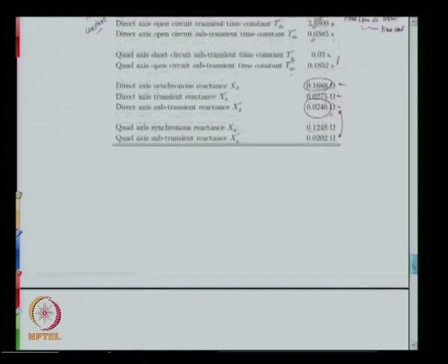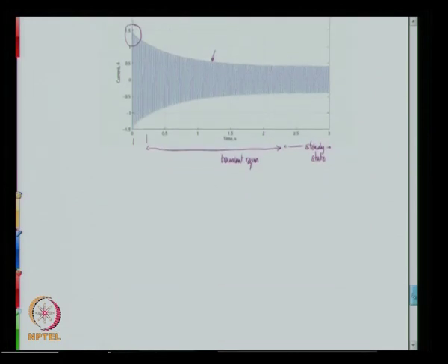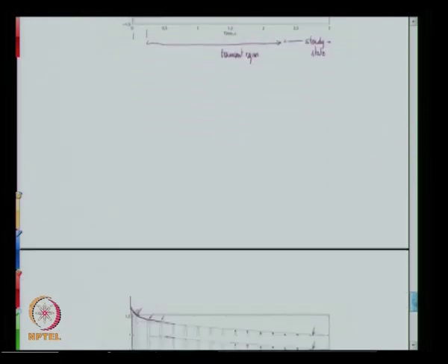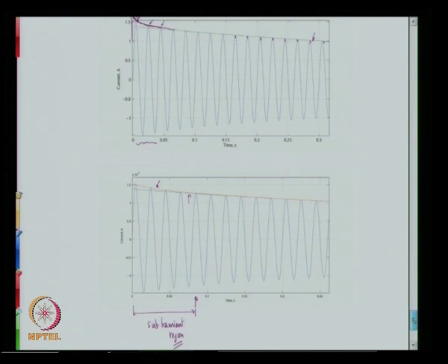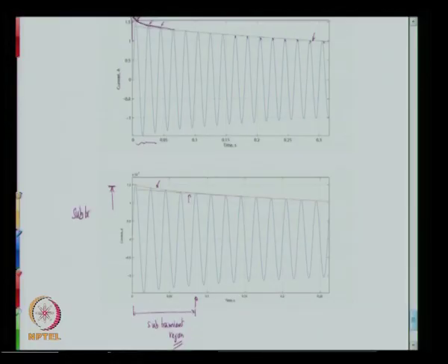So which is another interesting result, that in order to determine how much flow of current the system elements along the line, like circuit breakers and so on, have to withstand, one has to really look at the subtransient reactance.